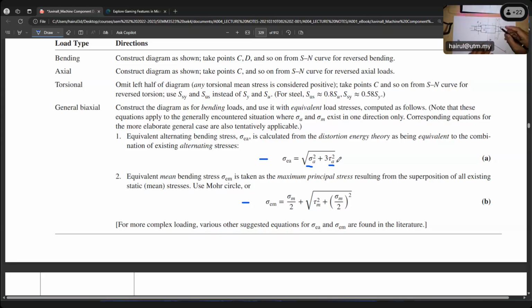So whenever, okay, notch, shoulder, we have notch radius. Groove, can you see? We have notch radius also. If this is the case, you cannot take, let's say even in your shear diagram, your moment diagram is the most critical here, moment maximum here. You cannot take this as critical because since we have a notch here and a notch here, you need to identify both. Understand that?